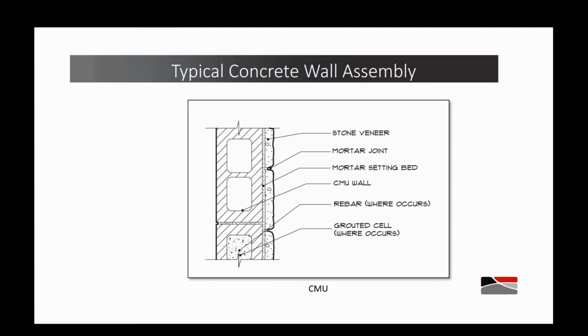What I mean by that is that oftentimes the masonry contractor will assume that the general contractor has cleaned it prior to his arrival on site. The general contractor in turn will assume that the masonry contractor will take care of that once he gets to site. And what happens often is nobody takes care of it. In our experience, if you have a poured in place or tilt-up panel wall and the issue of form release agent is not dealt with, it is not a question of if your stone falls off, it's a question of when it falls off.